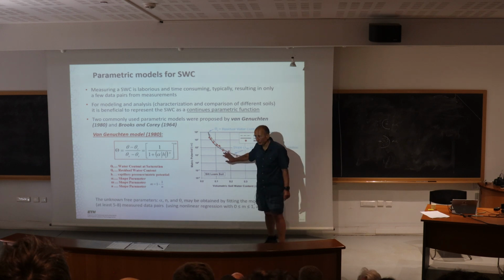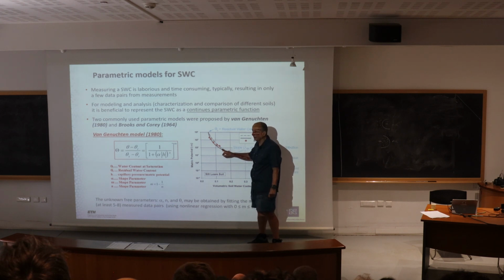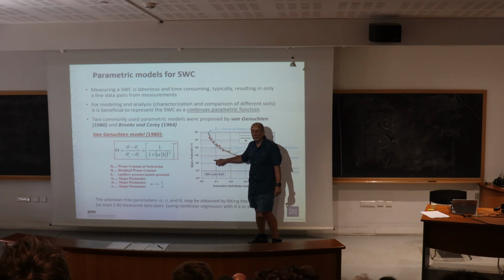He talks about hysteresis. So the idea is that depending on which path you take on a characteristic curve, whether you wet the characteristic curve or dry the characteristic curve, the path is not unique, and you may have loops, meaning certain pores will empty one way but will not empty the other way, and so you'll have some differences.